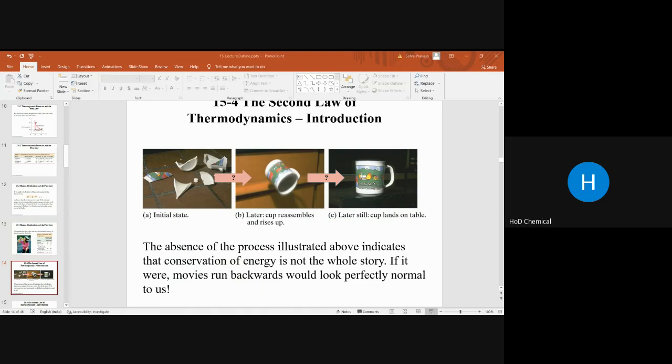Okay, let's see. In a frictionless reversible system, an infinitesimal increment of the entropy of a system is defined as the result of a transfer of heat to a closed system, divided by the common temperature of the system in equilibrium with the surroundings which supply the heat. It means that dS is equal to dQ divided by T. Different notations are used for the amount of heat and the amount of entropy because entropy is a function of state while heat, like work, is not.